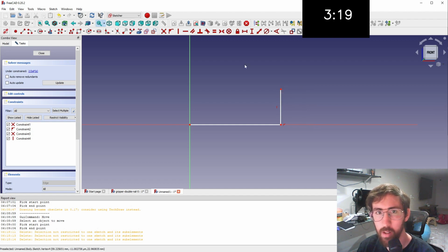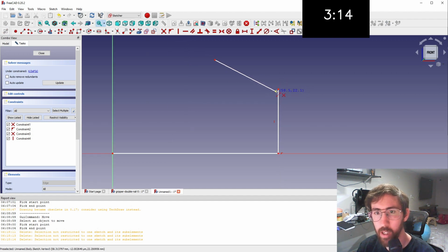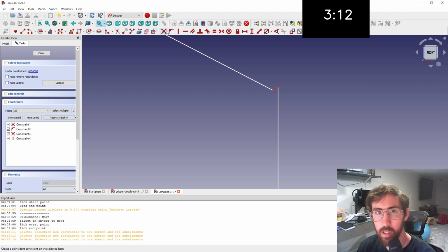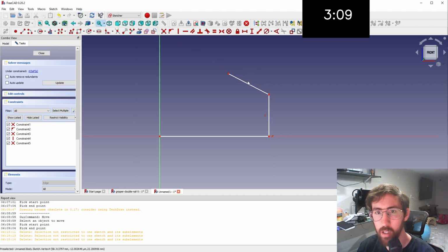precisely into things. Now I can draw a new line here, but notice that I've missed it and they're not actually connected. I can easily connect these by using this constraint here. And notice that there's no vertical horizontal constraint on this line, so I can spin it around. I want this to be horizontal. I don't want to line it up with my eyes. I just want to click the horizontal tool. We could go back to our line and we can make a rail.